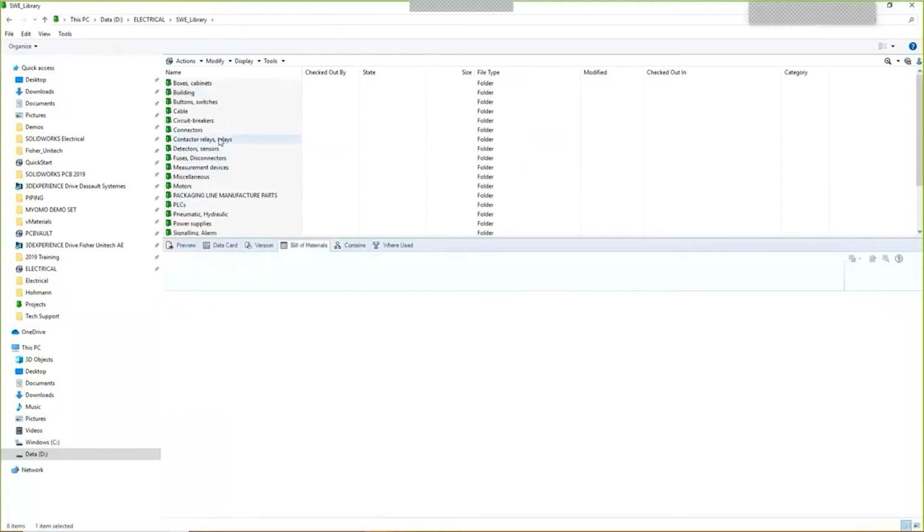All of your components that you load from your libraries, from the electrical component portal, or you create manually, are all going to be within that SQL database that SOLIDWORKS Electrical looks at. And then you're going to have a library that your production components are going to be part of. So you're only synchronizing the components that you actually use within the projects into the PDM vault.